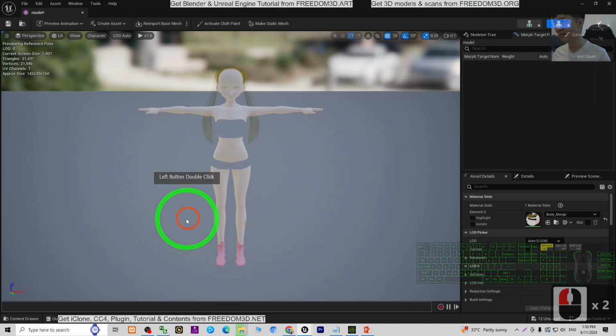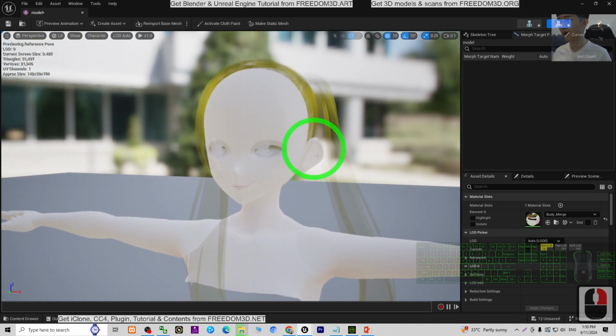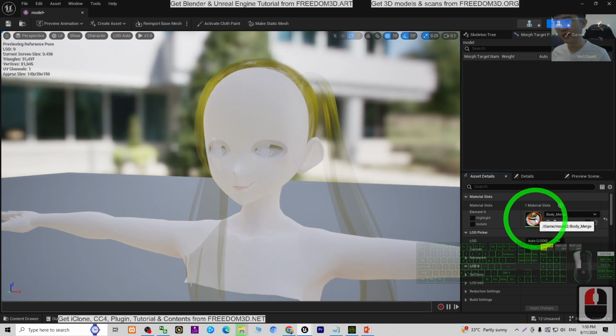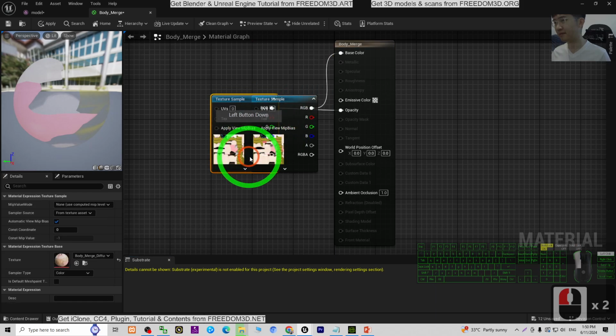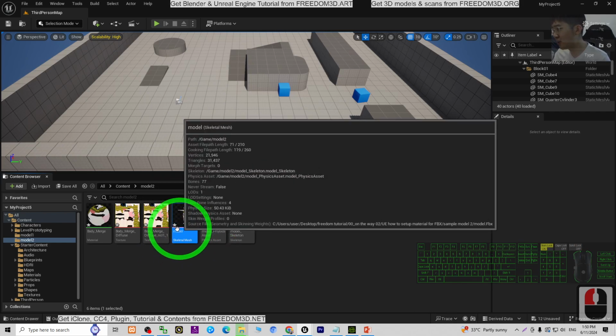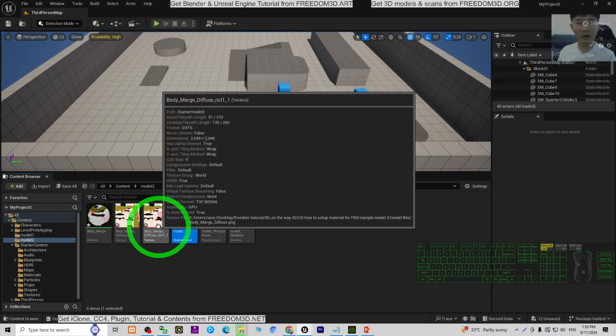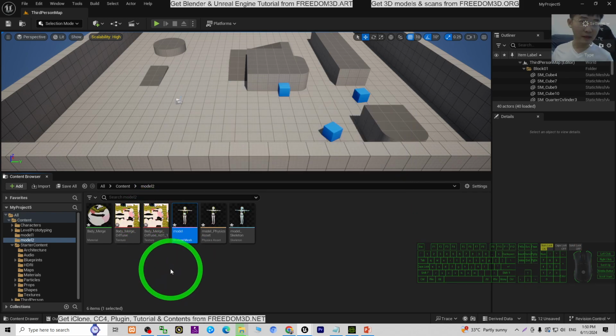Now this 3D model, the skeleton mesh, now you can see it is not set automatically as well. And the material is set here. You double click, you can check it. Then we just check here. The material is already automatically loaded just because this FBX file has embedded the material texture.